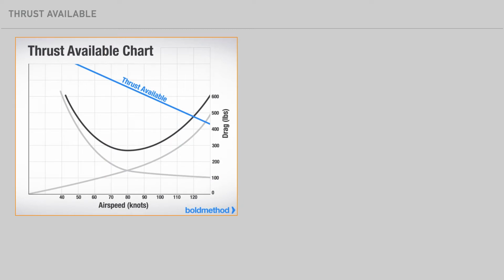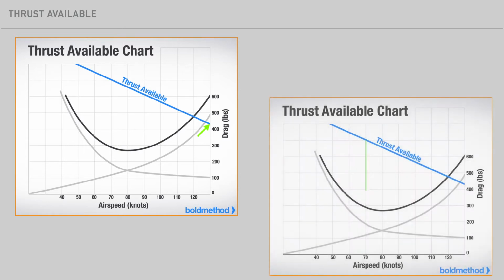Next, we will look at thrust and power over varying airspeeds. Beginning with thrust, we see the highest thrust is at the lowest airspeed since the propeller is at a high angle of attack. As airspeed increases, the angle the propeller blade makes with the oncoming relative wind decreases, which in turn decreases its angle of attack, and thus thrust decreases. The speed at which you have the maximum angle of climb is where the difference between the thrust available and the total drag is greatest. That is Vx. This is the speed at which you have the greatest gain in height over the shortest distance and is used to clear obstacles near the departure end of the runway.